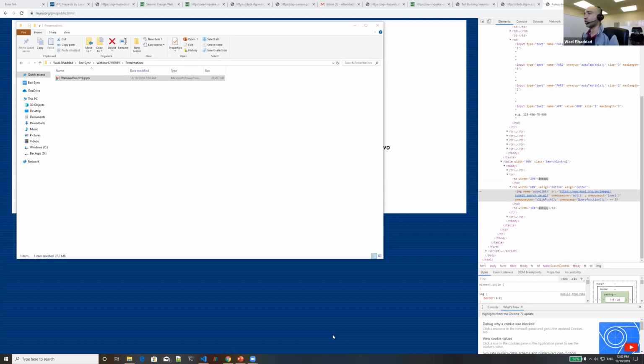But the problem is it won't be easy to get structural data for all the buildings in a region, for instance. Although in the SimCenter now, there are some tools that are exploring this, like using machine learning and AI to try to detect information about structural systems. For instance, we have a machine learning tool that tries to detect soft stories based on Google Street Views. And we have another tool to do interpolation. So if you know information about a group of buildings in a region, it can interpolate between them and give you interpolated data for buildings with missing data.